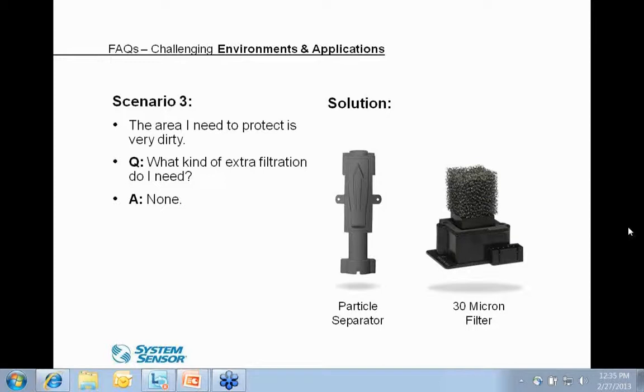The third stage of filtration is the chamber, which uses an infrared and a blue LED inside the chamber. If any particulate were to pass through the particle separator and then the filter, and enter the chamber, it's sampled by both sources. If it's a dust particulate, non-combustion, we reject it, and if it's particle combustion, we confirm it with the blue LED very accurately.